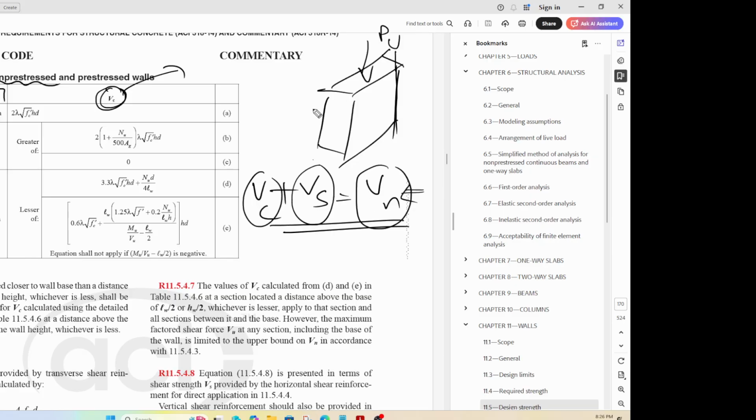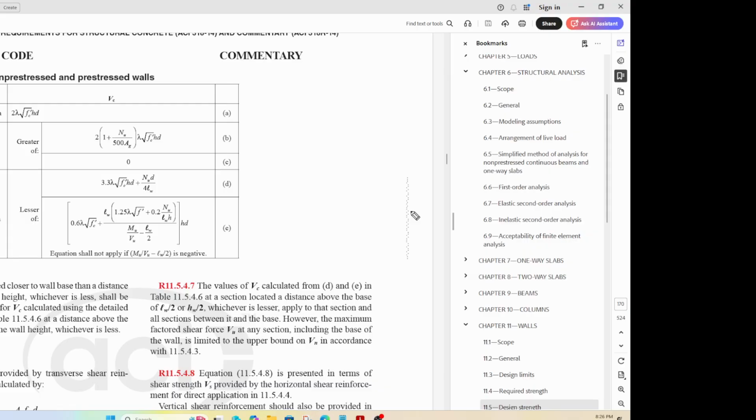When you apply in-plane shear, it is not just the concrete that is resisting. Maybe there is some transverse reinforcement, and that can also take some amount of shear. And your concrete, depending upon how strong it is, is going to take some amount of shear. The sum will dictate your nominal strength, right?